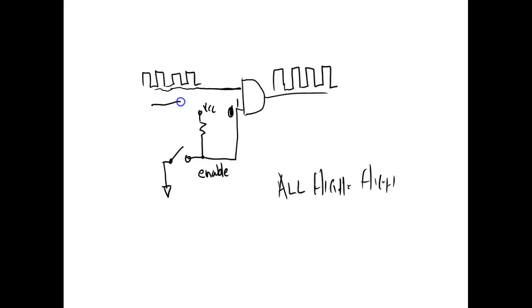What if I added another input? Well, now if I enable it, it acts like a 2-input AND gate with an enable input. If I disable it, the other 2 inputs are just flat ignored, right? You understand? So with an AND gate, no matter how many pins it has, I can use that enable input to either open the gate or close the gate. So that's why, mainly, we refer to these things as what? Gates.